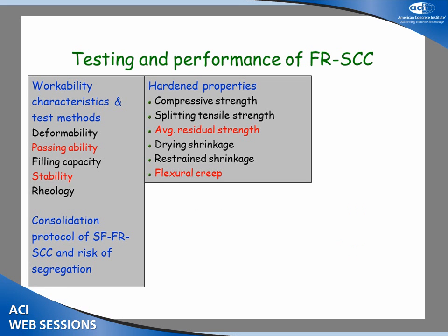So I'm not going to present all the results. We'll need a lot more time, but I'm just going to pick up especially on what is highlighted here in red. But the study involved a mix design using a very specific approach, which is based on the equivalent mortar thickness over the rebars and also combined with the steel fibers. We looked at different test methods, and I'd like to point out some of the test methods that were different than what you would do using standard ASTM tests, for example, J-ring or L-box. We looked at the rheology, the stability, the filling capability, etc.